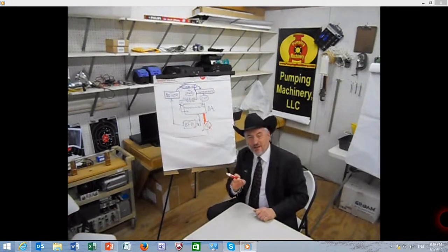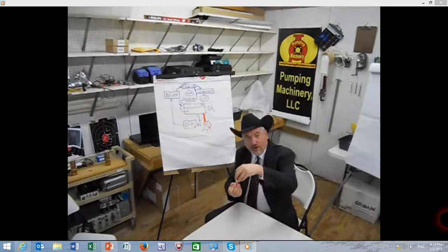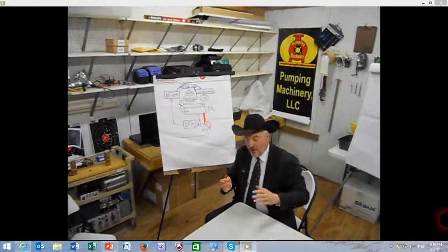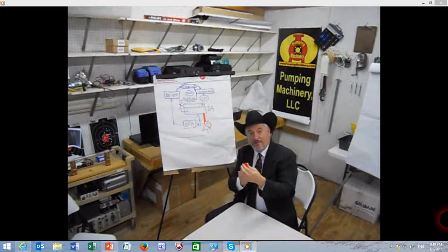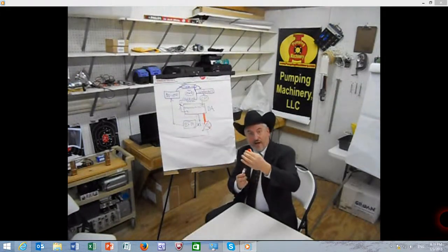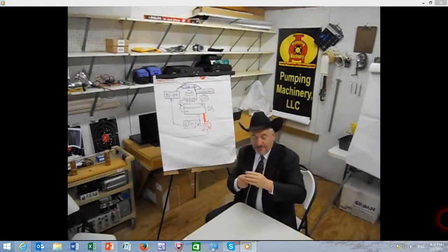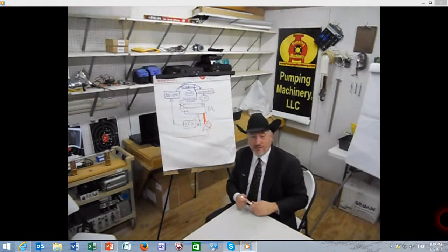If this water gets below vapor pressure, it will flash. But flashing is tricky. Normally, we have an open container, and we reduce pressure in the container, the fluid will flash, but if the container is constant volume, it has no place to go. If we have a piston on top of the container, and the pressure is reduced, then it's a constant pressure situation where the top of the can will lift up and will reach the greater volume to accommodate the expanding vapor. Well, in our case, is it a constant volume or constant pressure?